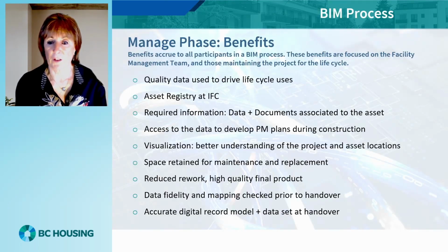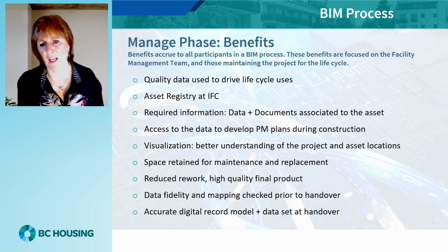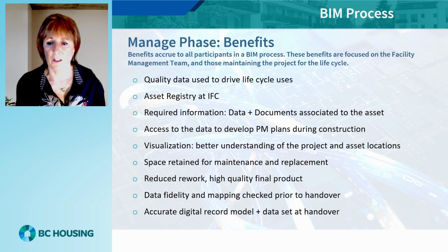There are many benefits for the FM team from following a data-driven digital process. The high-quality data can be used to drive multiple different processes during the life cycle. It will generate a preliminary asset registry at IFC, aligned with additional installed asset information that is to be provided during construction. This provides a clear understanding of what will be available at handover. Early access to this information supports development of the preventative maintenance plans during, not after construction.